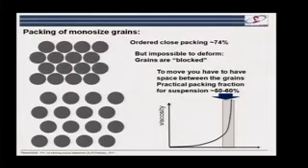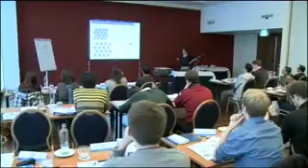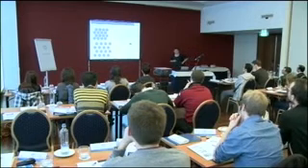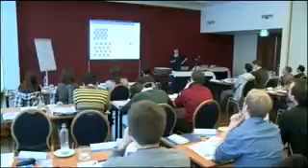So we're going to look first at this cement paste level. We need to think about this process at the beginning where the cement grains have to be able to move in the water. Now, if we take a very simple example of monosized grains, if you make a sort of close packing arrangement like this, a close packing arrangement of spheres, you can show geometrically that the maximum volume of solid you have can go up to 74%. That's absolutely the maximum for a close packed structure. Now, if we had something close packed like that, that's completely solid. You can't move anything in a structure that's that close packed.